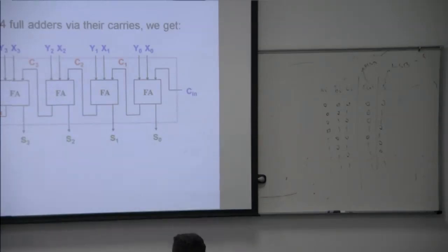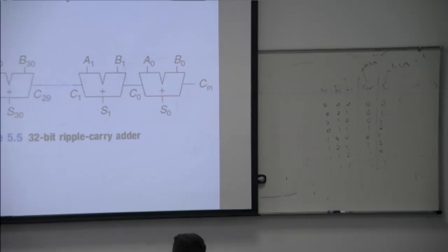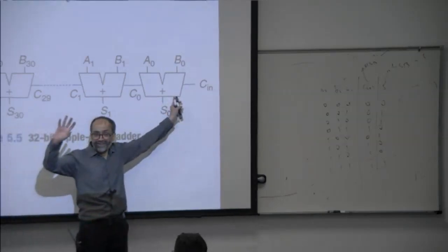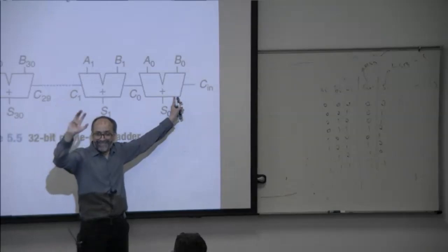Should we proceed? Okay. Now, if we want a 32-bit ripple carry adder, how can we design it? How many stages? 32 stages, and for a 64-bit adder, similarly 64 stages. This method is called a ripple carry adder. And if you look at each adder, how many gates are inside? Remember, there may be some exclusive OR gates.